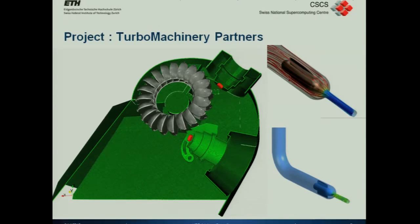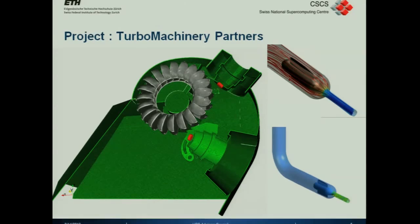Over here you have jets. Water comes down, there's a lake on the top of the mountain, the water comes down a pipe, it comes out of this jet here, hits this bucket, and then it splashes out. Now the buckets all spin round, and the shape of this jet actually plays quite an important part in the momentum transfer, the energy transfer into these buckets.